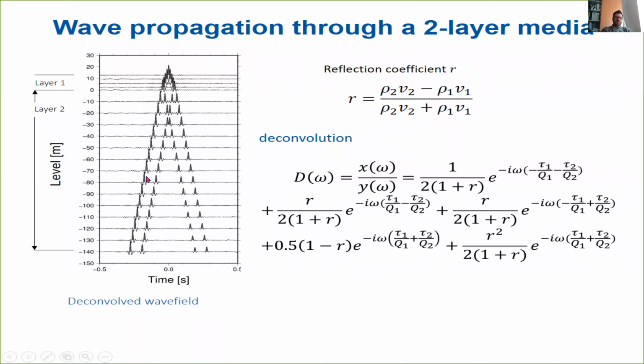If we assume that this is my propagation in the underground and this is my propagation in the building, we can calculate a synthetic seismogram, using as a reference the recording on the top, because we know that this reference is only showing us upgoing and downgoing waves, removing, like we have seen before, the effect of the shaking of the building. We can try to see, if we take the ratio between the recording at the bottom and the recording on the top, what the transfer function looks like for these waves. Which kind of pulse will I recognize, describing the propagation of the waves?